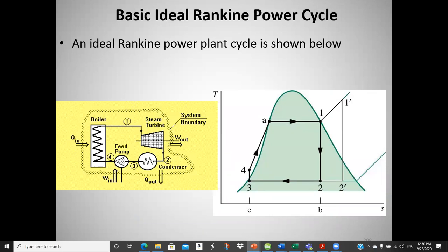So if we look at a simple, basic Rankine cycle, this is like Thermo 101 stuff, right? But it's still got the basic components. We've got a boiler, a steam turbine, a condenser, work coming out, and a feed water pump. We have to condense this stuff because you can't pump a vapor. You can't use a compressor; they take way too much energy.